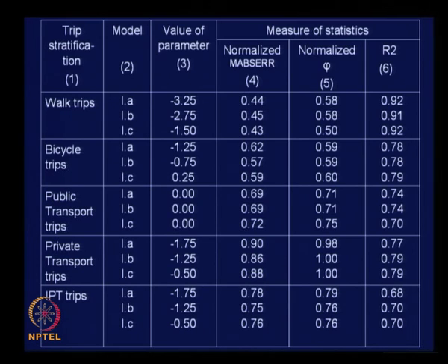Clear. So, that is how we need to understand the effect of the bundle of the factors that influence trip distribution. It is not simply only the distance; travel time or cost altogether is taken into account while deriving these parameters. And interestingly, you can see that in respect to public transport, which is bus in this particular city, travel deterrence is shown as 0, no deterrence at all. Could it happen? For any mode there should be some deterrence, isn't it. This implies that people do not mind travelling by bus any distance in the city.